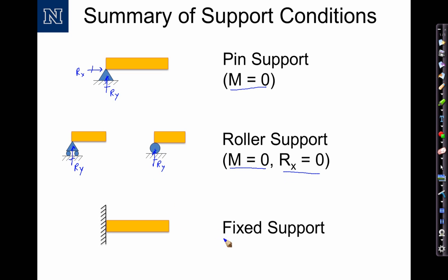And lastly, we have a fixed support, such as at the end of a cantilever beam, which constrains all movement and therefore can develop a reaction in the x direction, in the y direction, and it can also develop a moment.